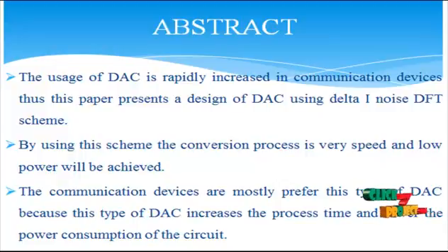This project presents a 3.5 gigabit 6-bit current sensing digital to analog converter with accurate circuitry to assist testing in a 1 volt digital 28nm CMOS process. The DAC uses only thin oxide transistors and occupies 0.03 mm, making it suitable to be embedded in VLSI systems. Design for test standards for IC design add certain testability features to the hardware design.